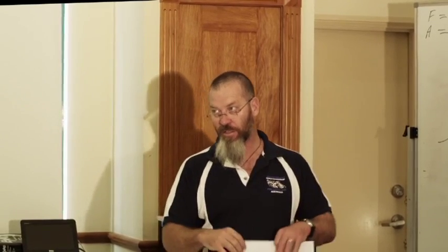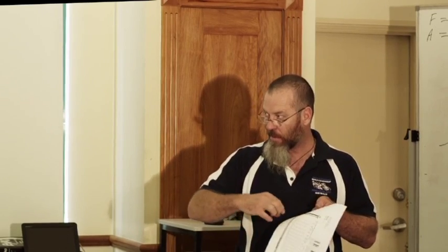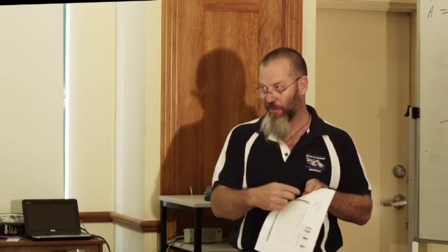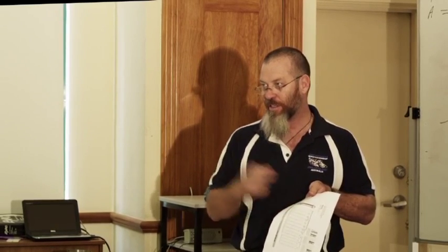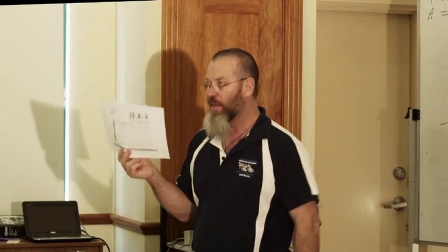Now, when you read 1684, the 90 mil plate, the minimum distance in from the edge for that hole for it to work is 25 mil. 25 plus 77 plus the other 7 mil for the side of the hole exceeds that 90 mil width. So technically, if you follow this and that, you cannot use Dynabolts on the outside edge of a slab.